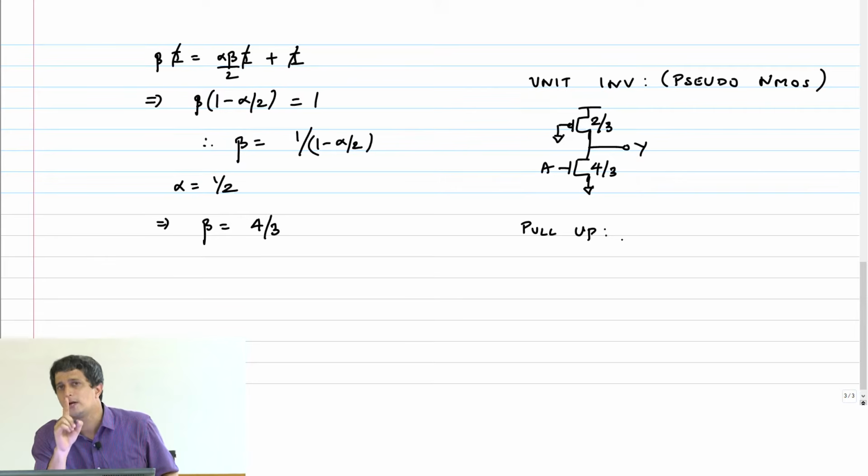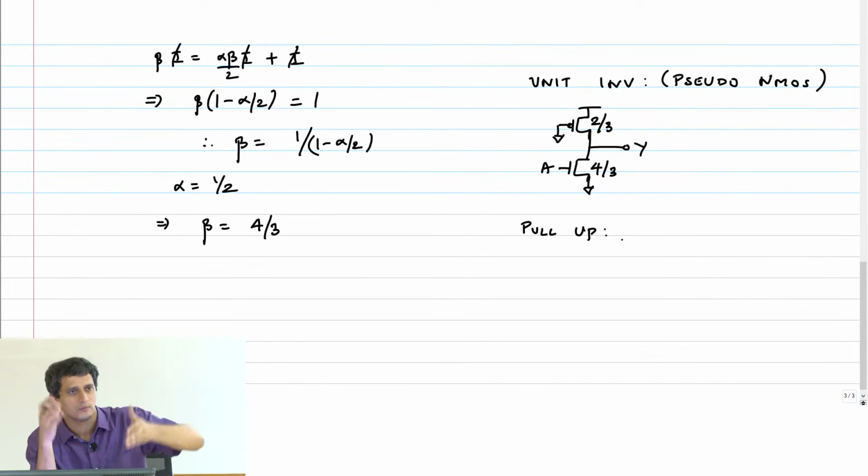Now I'm going to refine my definition. I'm not going to say same drive strength, but rather that it can provide the same current to the load capacitor for charging or discharging. Drive strength is slightly vague. You might think it's a resistance. But because of the pseudo-NMOS problem, where I have currents from the PMOS also, I'm going to change the logical effort definition slightly to say it is the ratio of gate capacitance compared to a static CMOS inverter which can provide the same current to the load capacitance for charging or discharging.